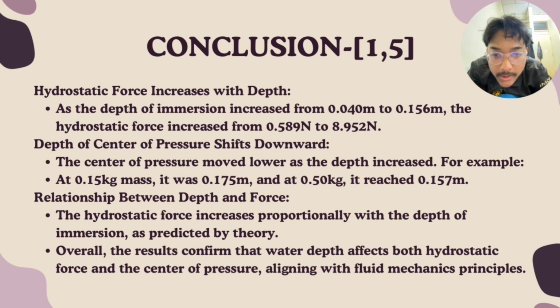Alright, for the conclusion, hydrostatic force increases with depth as the depth of immersion increases from 0.04 meter to 0.156 meter. The hydrostatic force increases from 0.589 to 8.952. The depth of the center of pressure shifts downward. The center of pressure moves lower as the depth increases. For example, at 0.15 kg mass it was 0.175 meter, and at 0.50 kg it reached 0.157 meter.